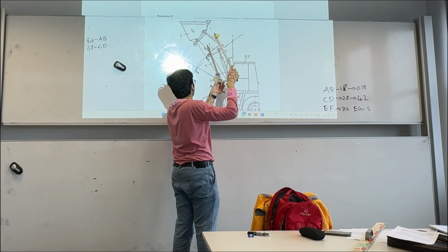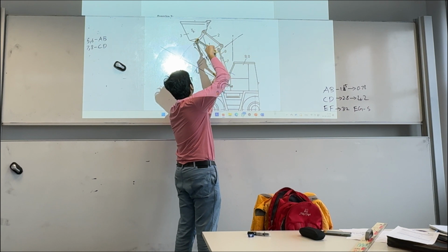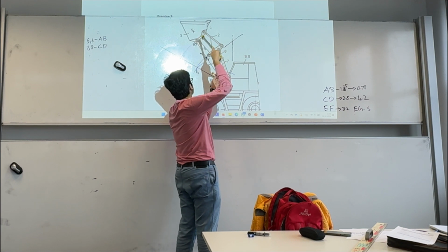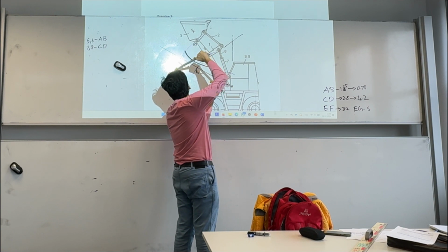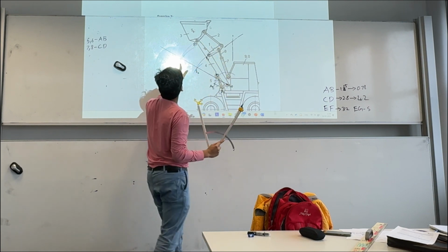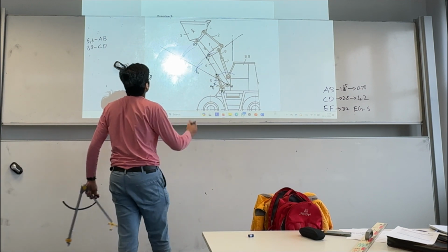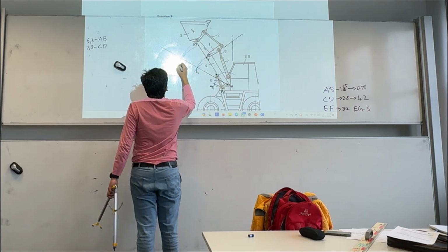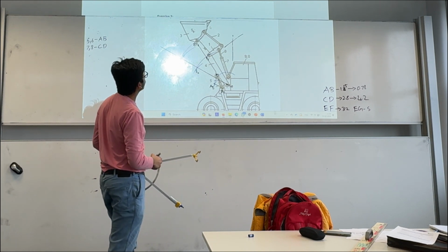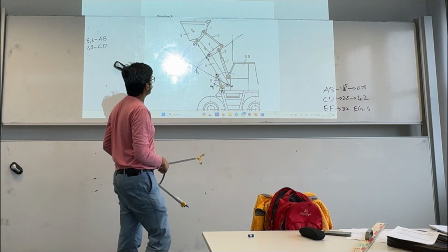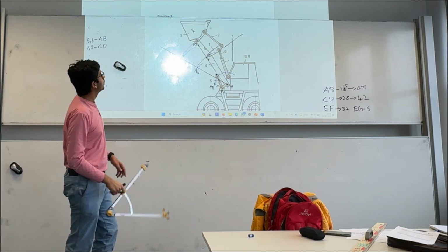So from A1, take A1G as radius, move to A2 as center, find the intersection point. That is G2. Cool. We shouldn't even use the ruler to construct, but we should use the points. Yes, the points are better, and then finally connect up everything with the ruler.